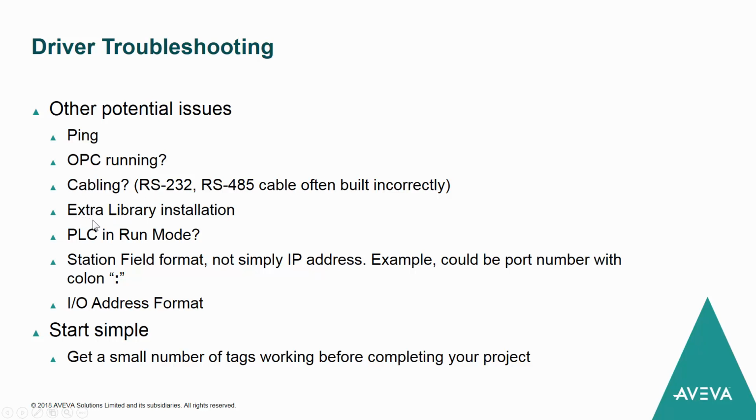Sometimes for certain drivers, you need extra libraries installed, DLLs, things of that nature. Those particularly come into play when you have drivers for hardware cards that are installed in the computer, things like DeviceNet, CAN, some other drivers where you might have Profibus, ABB Total Flow, things of that nature. So you might need extra files installed. Is the PLC in run mode? Some will not communicate if it's in stop or program mode. So pay attention to that.